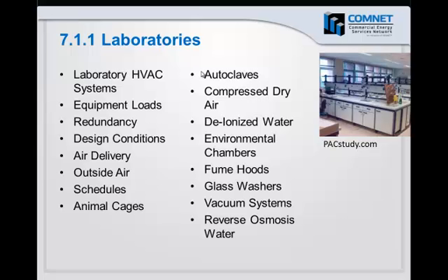The only case where that rule might not be followed is when, let's say, you have 100 tons of load and the proposed design has two 75-ton chillers that sequence, and one 75-ton chiller is adequate to maintain cooling in the critical spaces. In a case like that, the rated building can be modeled with the proposed equipment.